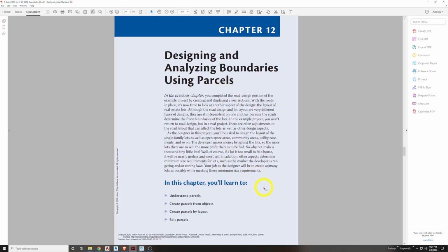I'm using those words a bit interchangeably, okay? So when we use some Civil 3D tools to design parcels, a land developer might need to squeeze in a certain amount of parcels into a design. Other aspects to determine, maybe there's a minimum frontage size for the lots. The market might have certain aspects, like we'll look at here soon, with zoning and different planning laws in your geography to determine what kind of lot density and size and various access things and amenities you need to put on the lots.